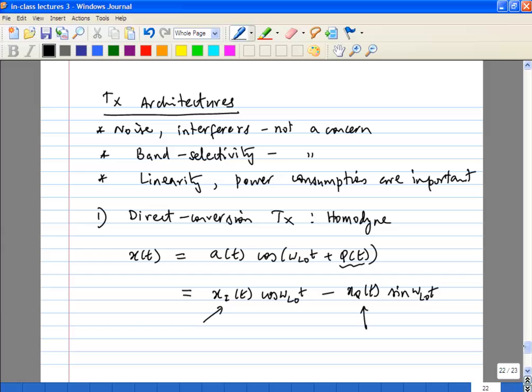So what happens is baseband produces I and Q signals that are sent through a DAC, and the DAC output comes as an analog form to your transmitter, in either voltage or current form, doesn't matter. Baseband will do both phase modulation and amplitude. Yeah, baseband can handle everything. And the output will have two sets of signals, Xi and Xq.